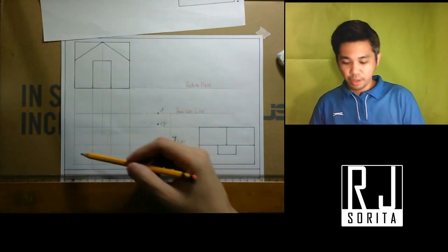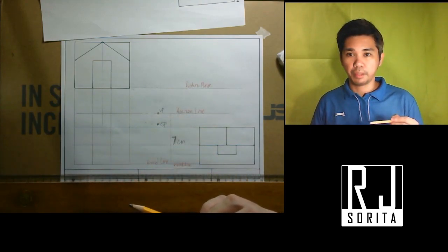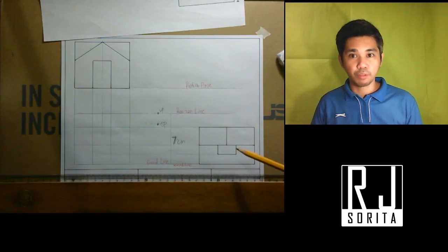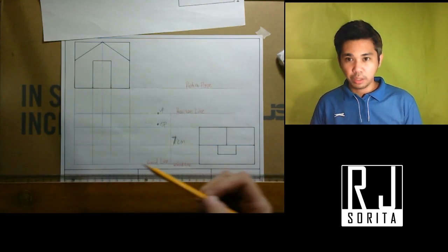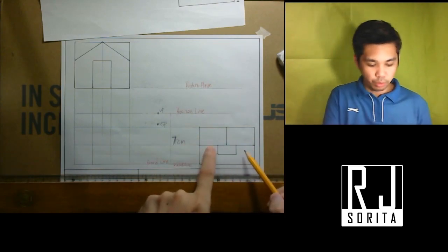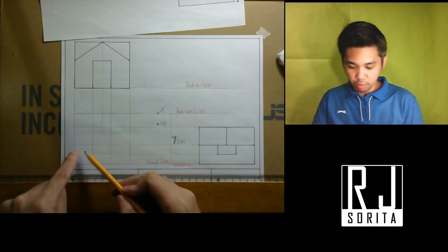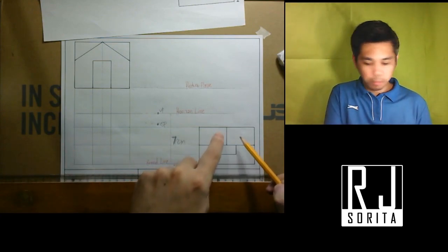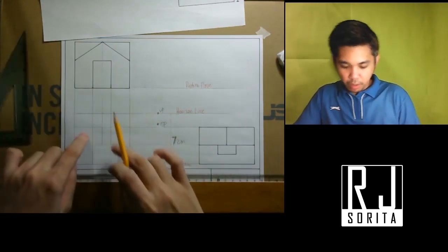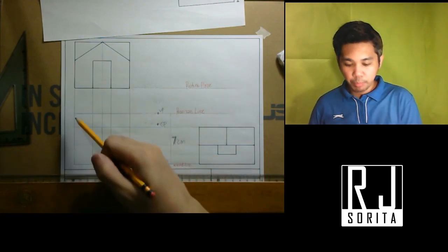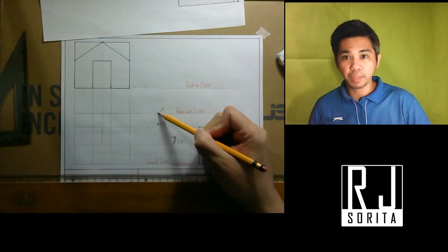So if you have noticed, there are lots of boxes created, but what we are actually interested in is the look of our front view. So from this one, we should have a look which will form our front view. As you can see, there is a plane that looks like a U. There is a couple of boxes here that looks like a U. And then we have two boxes here. The intersecting points should be connected to our vanishing point.